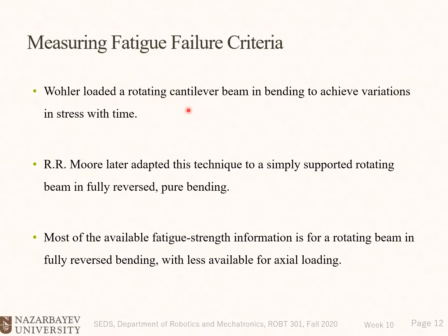So there was a cantilever beam, there was a constant load at the tip of the cantilever beam, but the cantilever beam was rotating. Okay, so once we have this rotation at the specific cross section, let's say at the base, where we have maximum bending stresses for that cantilever beam, for one specific point, as that point is rotating, it goes from the maximum positive stress to the maximum negative stress, or from the maximum tensile to the maximum compressive stress.